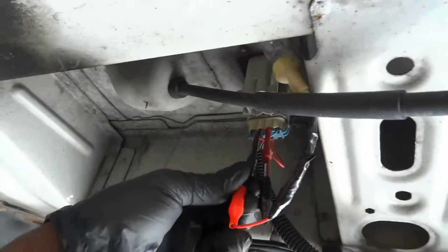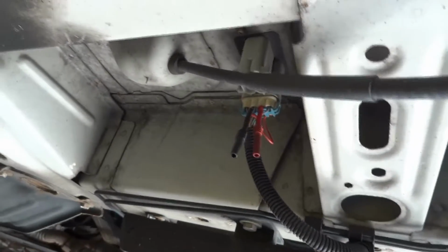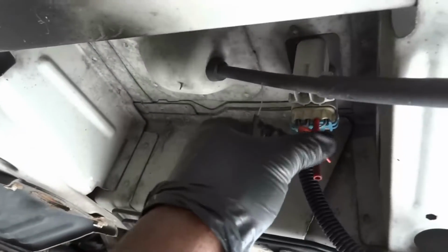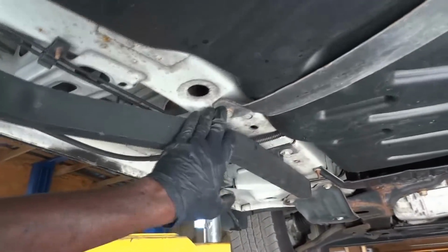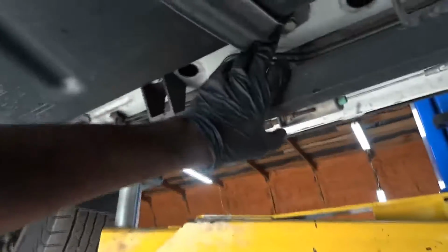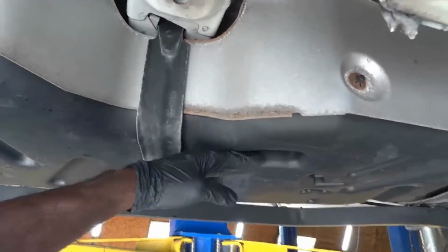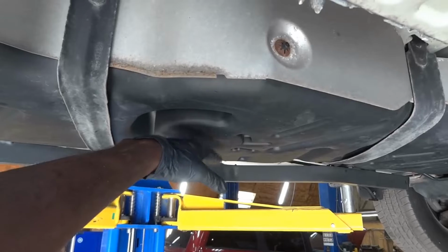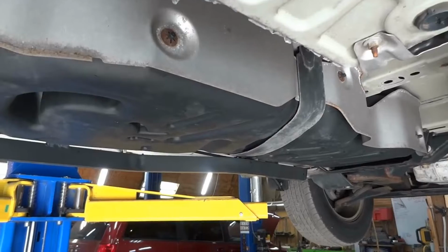So now I'm gonna remove my test light. I'm gonna remove these back probing tools over here. Now, to remove the fuel tank, we're gonna have to undo these straps. So we're gonna undo this strap over here, and then there's another one over here. So we're gonna undo this bolt, okay? And there's a third one over here. After we undo all these straps, we're gonna put a transmission jack below the tank. We're gonna lower the tank a little bit so we can get access to the vent solenoid, okay?